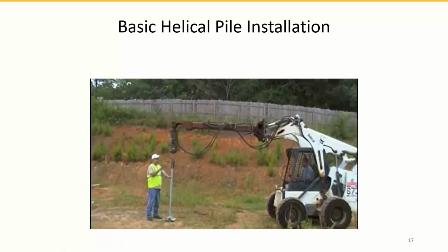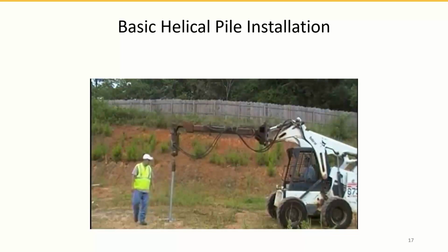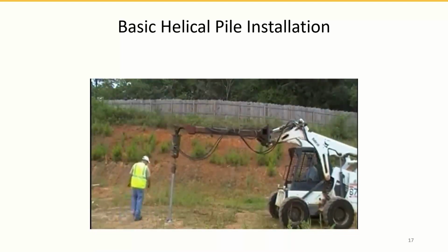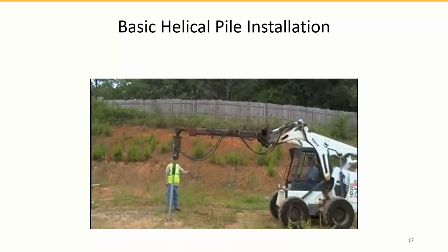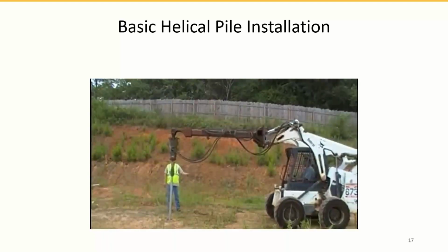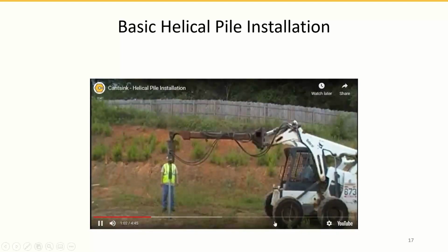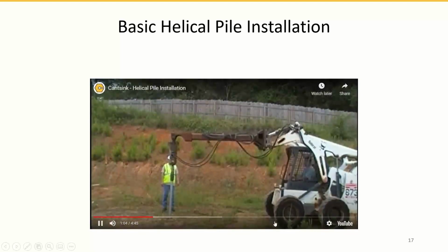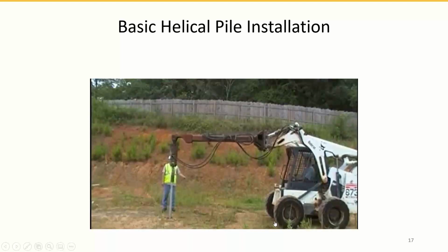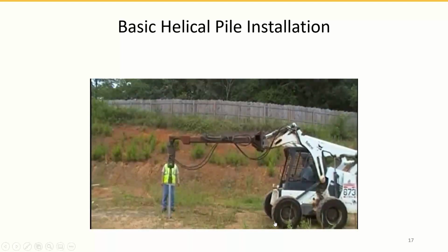And then he's just going to screw it into the ground. That helper helps with putting the helical pile in place and bringing the extension. He also helps guide the machine operator to make sure the pile is installed plumb. You see, he's screwing the pile in right now, and that's a 5-footer, like I said, just a single helical pile with a single helix.